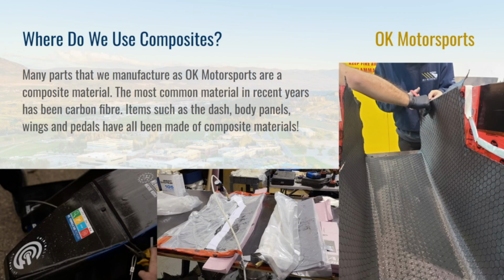That's after a wet layup and then inside of a vacuum bag. So after we've laid the fabric onto the airfoil, put the resin into it and then put it in the vacuum bag in order to provide compression when we're curing it. And that third one, that larger picture, is the hood. So that's the outer layer of the hood inside of the tooling. That's before any resin is put onto it. So that's just the fabric itself.